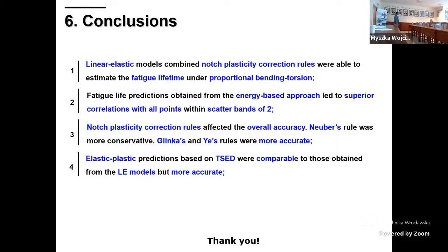Yeah. Thank you. Maybe if I can just add a small comment. Well, it all depends on the core, I mean, the predictor of fatigue damage. In this case, if we look at the Smith-Watson-Topper or the other formulas, they are still tailored for homogeneous materials like steels. But of course, we can propose a much more complicated damage predictor for composite materials, I know, short fiber or long fiber.